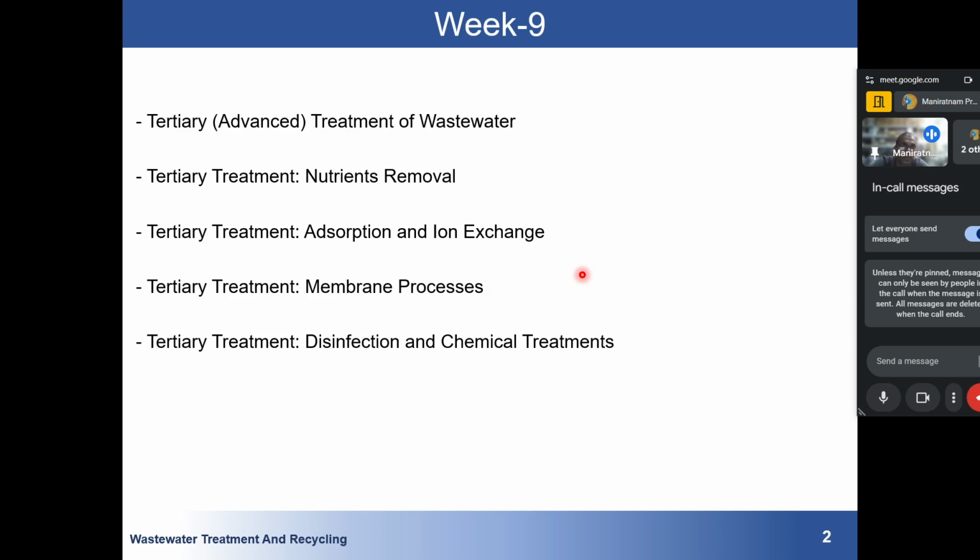Now there, we should control the nutrients, because we know that nutrients, generally phosphorus and nitrogen, may lead to production of algae. So we don't want algae in our system. The nutrients should be removed. Then we know that there might be some heavy metals. If you recall my previous discussion, I was discussing the chromium industry, that is the leather industry, where they use chromium. So the chromium should be removed. Chromium can be removed by several mechanisms, and generally chromium is removed by precipitation.